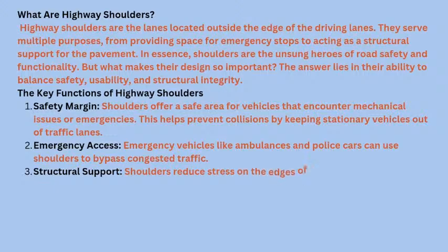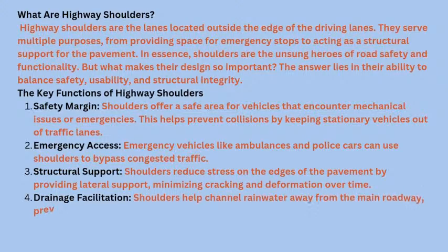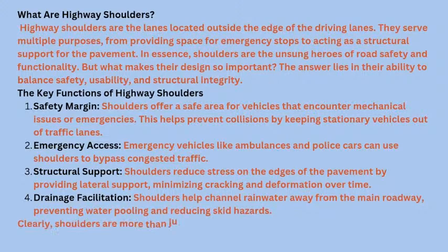3. Structural support. Shoulders reduce stress on the edges of the pavement by providing lateral support, minimizing cracking and deformation over time. 4. Drainage. Shoulders help channel rainwater away from the main roadway, preventing water pooling and reducing skid hazards. Clearly, shoulders are more than just extra space. They are critical to the overall highway system.